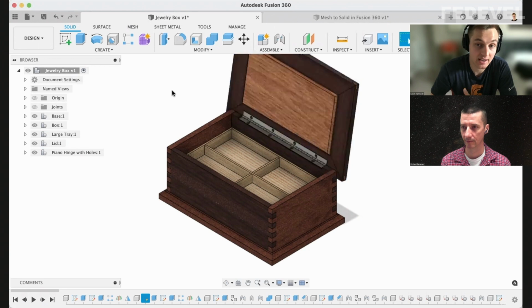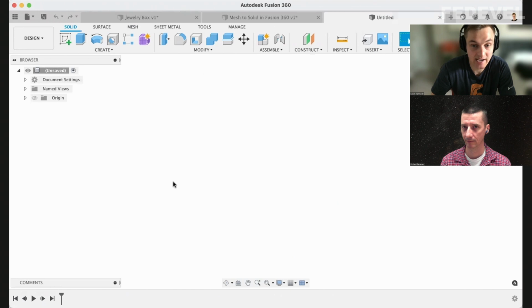Now, on the flip side, if you take the bottom up approach, that means you're going to create a new design file for each individual part. And then at the end, you're going to insert them into an assembly. And so there's disadvantages to that, particularly when it comes to referencing other parts. It can be a challenge if you're not working with the other designer or engineer closely, or if you forget what you maybe dimensioned something. Now, Fusion has, in my mind, solved this most elegantly compared to other CAD programs.